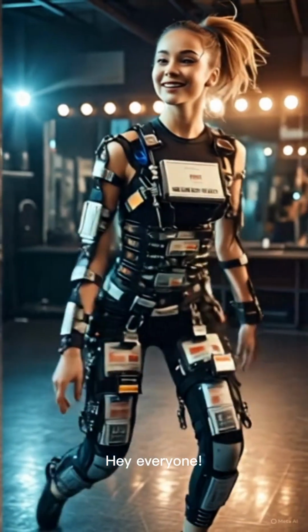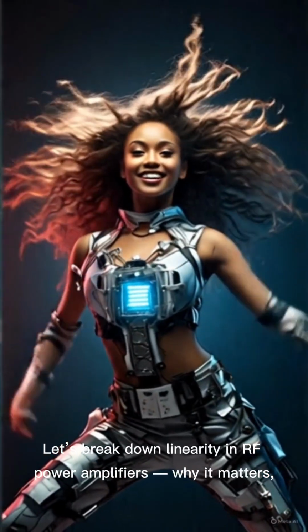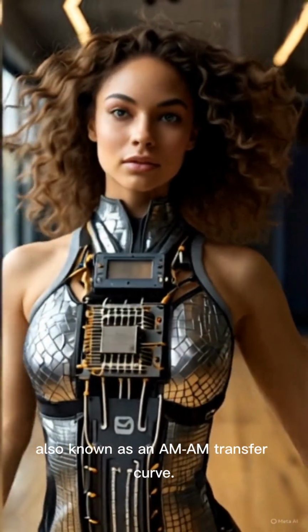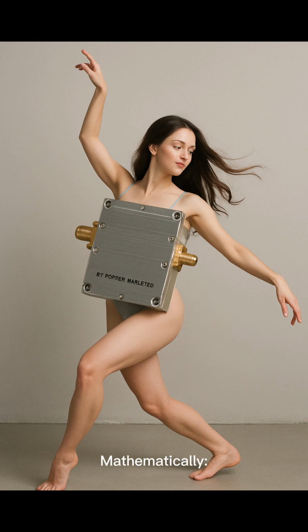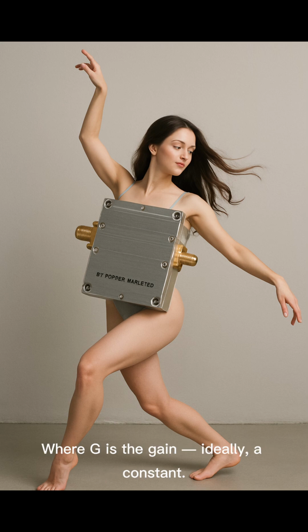Hey everyone! Let's break down linearity in our RF power amplifiers, why it matters, how we measure it, and how to estimate it from a real-world gain curve, also known as an AM-AM transfer curve. In our RF systems, linearity means the amplifier's output signal is a clean, scaled version of the input. No distortion, no compression. Mathematically, output voltage Vout equals gain G times input voltage Vin, where G is the gain,